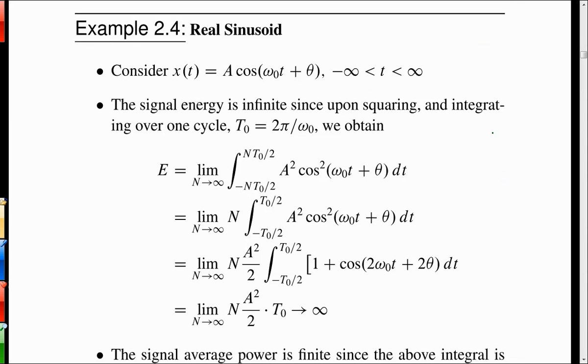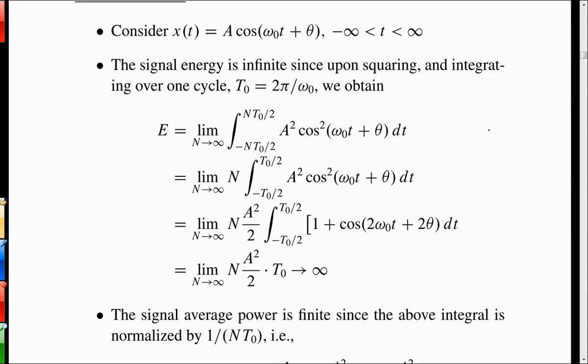So just to prove through that, I took the definition here and checked the energy of the sinusoid, and yeah, that goes off to infinity. Does anybody have a problem with that? You square a sinusoid, or take the magnitude squared of any signal, and it's always going to be positive, right? And if it's periodic, so it runs on forever, what happens when you integrate something that's always positive? You get infinity, right? So whether it's a square wave or a triangle wave or a cosine wave, and this just validates that by integrating the integral of a cosine function squared.